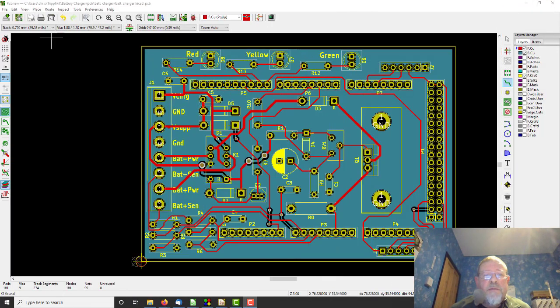Okay, done some final checks, including realising I had the relay on the bottom surface of the board. Would have worked because it's symmetric down the middle, but I like to have things right. So I corrected that and retracked that, and looked on the PCBWay website. They just want Gerbers and drill files. So let us create some Gerbers.